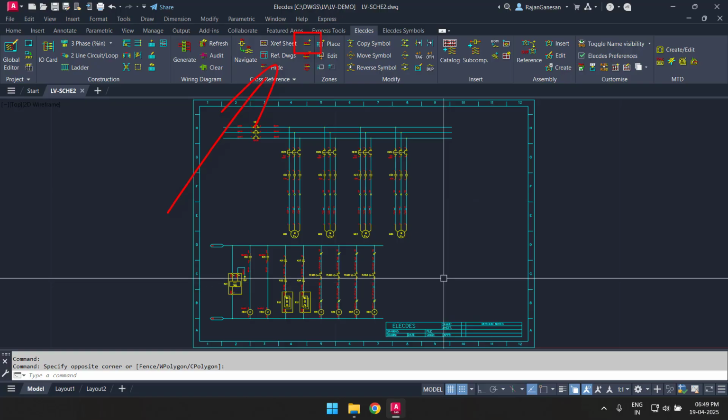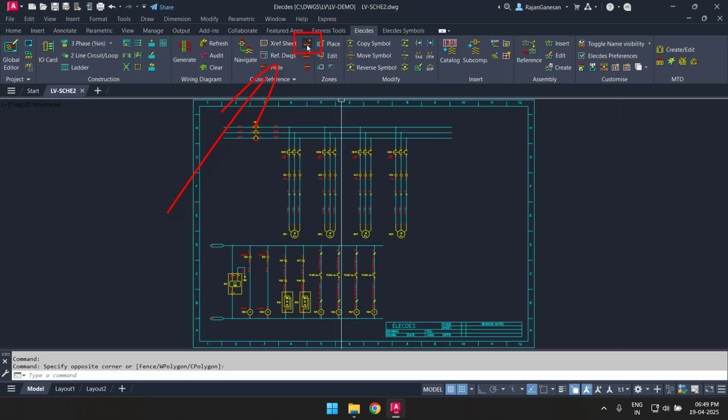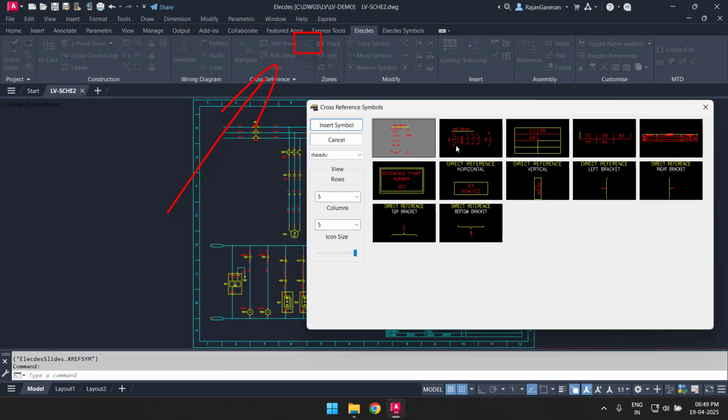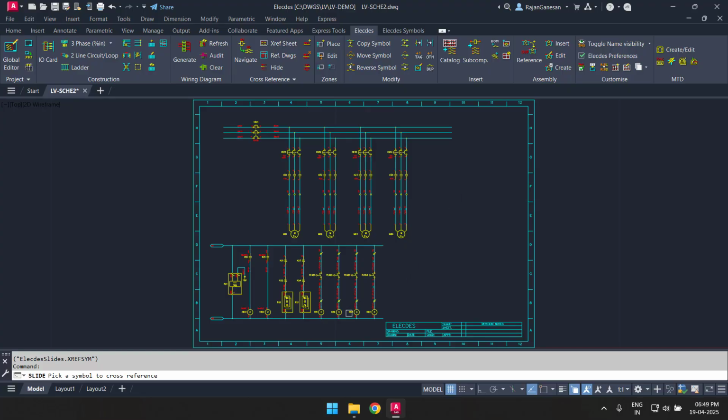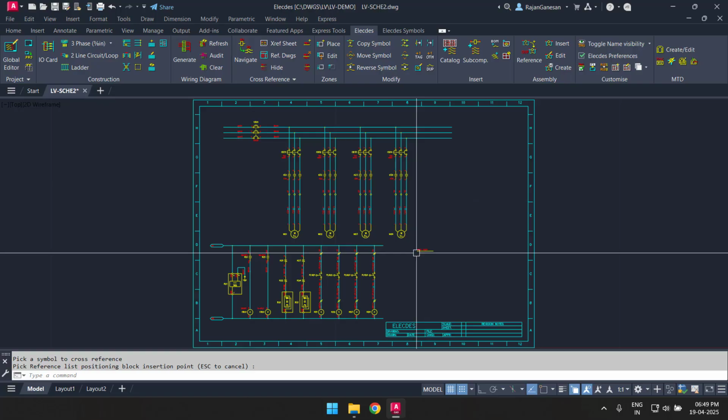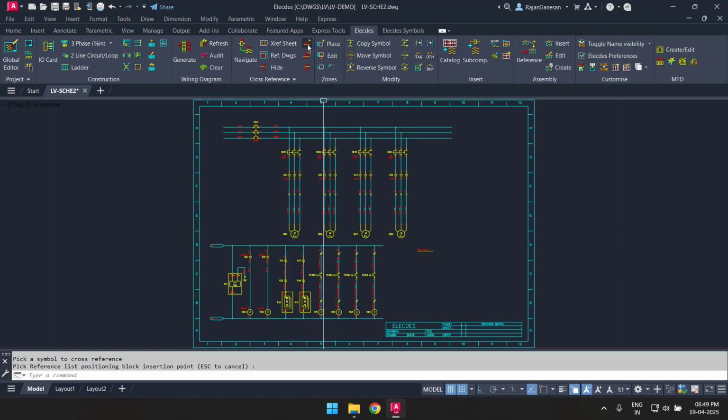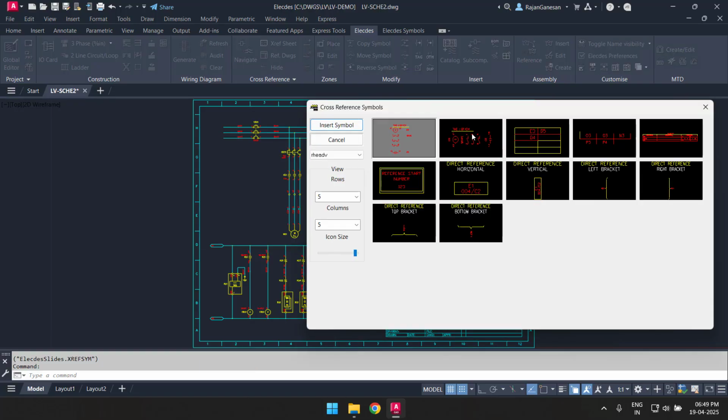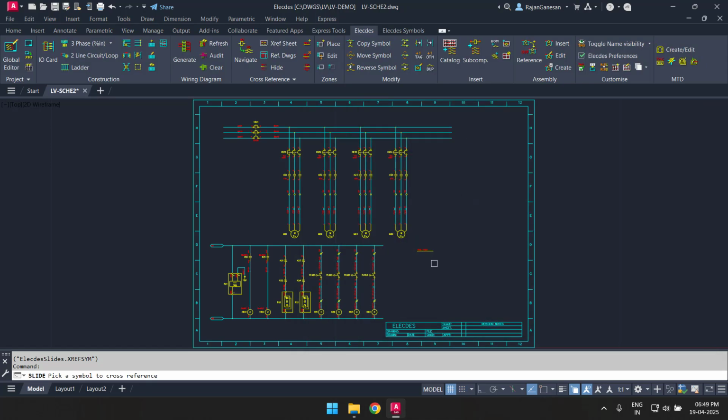Cross-referencing of families of subcomponents often requires a table to be positioned and created. I'll insert a table header. A table header needs to be linked to a component for the family that needs referencing. I will select the relays K24 and K25. I'll position the headers in some space on the side of my sheet.